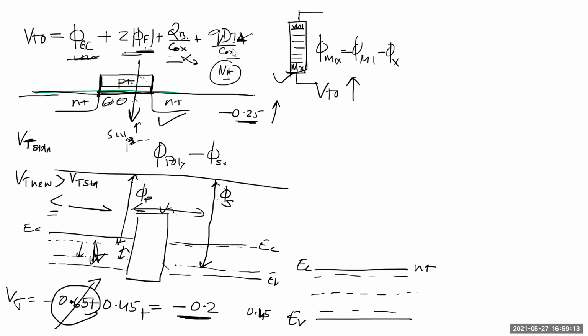So if you won't put the SiO2 layer but poly and metal, what will happen to the CMOS? You mean the thin oxides for this? I don't understand the question. So you're saying poly and metal. So what's your structure? You have this N plus, P plus. So you don't want oxide here? You want just poly here? Is that what you're talking about?